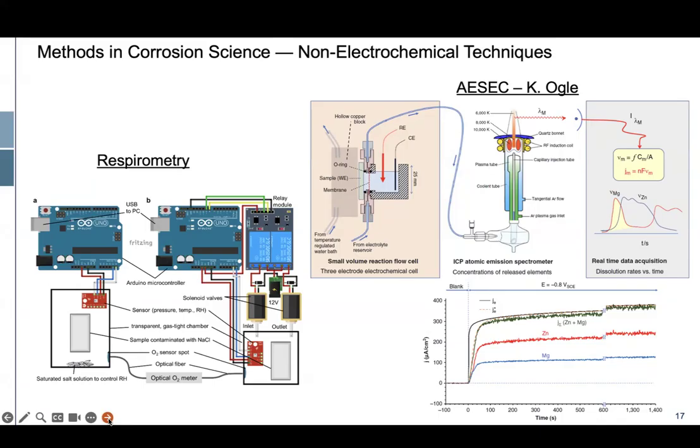In an alloy, you have multiple elements. What you measure, the mass loss or anything else, will be the total corrosion rate. We don't know how much the alloy composition is changing, because different elements can dissolve at different rates. This technique is a very powerful tool which uses an ICP atomic emission spectrometer, which can produce plasma, and we can see how much magnesium or zinc is dissolving, or this can be applied to any material. So this is an example from a paper.